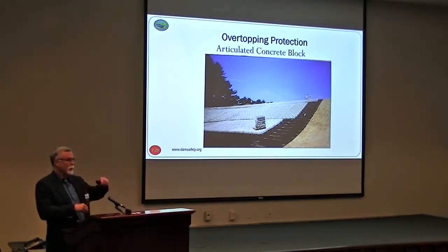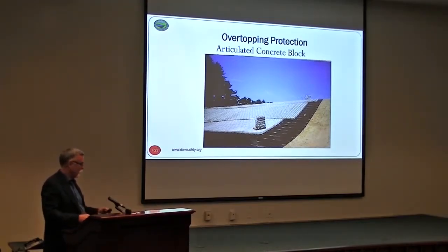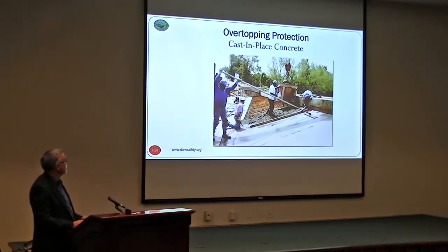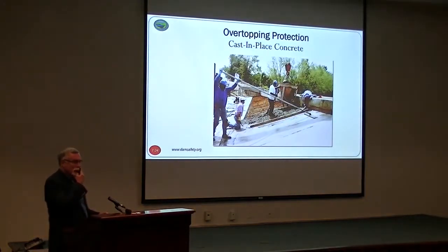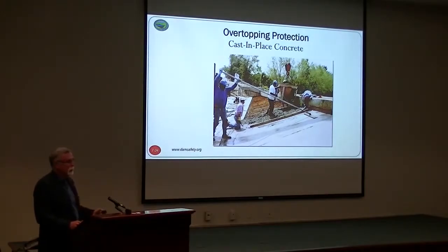They're good for limited depth of water, and you've got to have uniform flow over them. You can't have a spillway that's converging. With these blocks, you've got to have a uniform flow over them for them to work properly. And the worst case is conventional concrete. You generally don't want to use it because it's more expensive. You've got to have joints. You've got to have reinforcing wire, but that's another method that you have to consider.